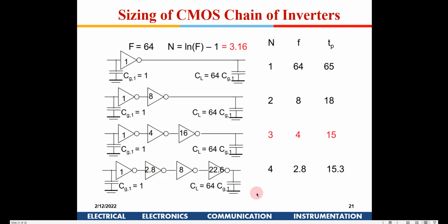One question. Yeah, ask me. In order to make the propagation delay minimum, this sizing has to be made, correct? Now, for a single digital IC, everything would be mapped onto a single wafer, and the same nanometer technology is normally used, right? So for sizing different gates with different widths, is it not cumbersome from the fabrication technology?